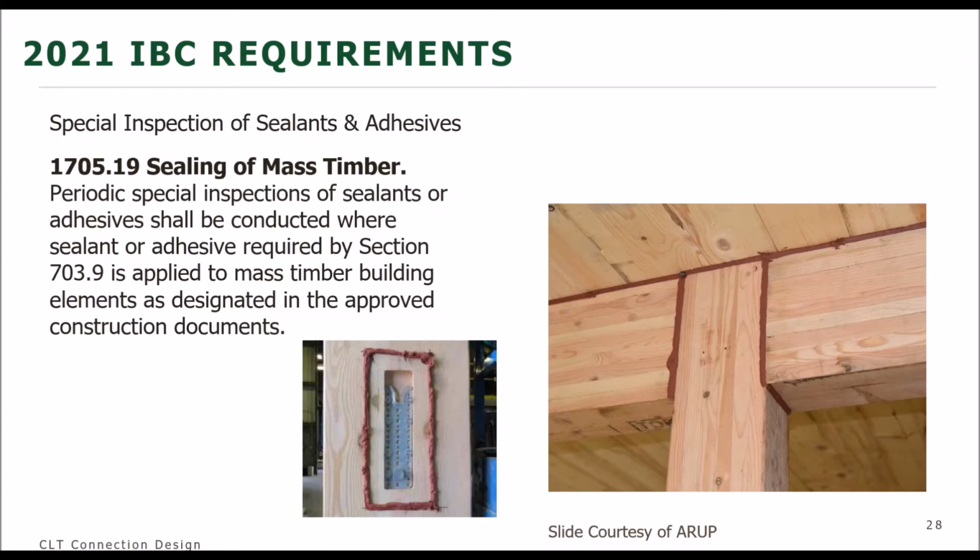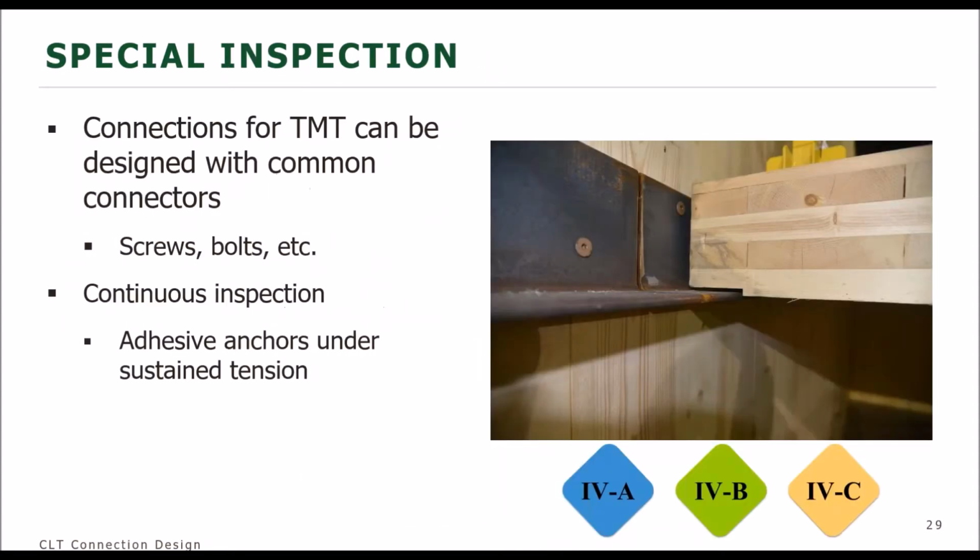1705.19 does require special inspections of sealants or adhesives as they are installed. You can see the adhesives in this picture, but typically after installation, that's not something that you would leave exposed. From an architectural standpoint, it may not be the nicest thing to look at.